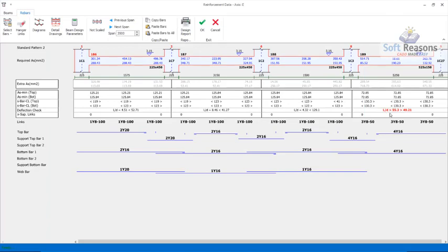So we are having the deflection check failed right here. Deflection check is failing right here. Okay, you should know this beam. So this is the concealed beam. It's because of the 150 thickness that we assigned to this particular beam. So there's a deflection right there on the beam.